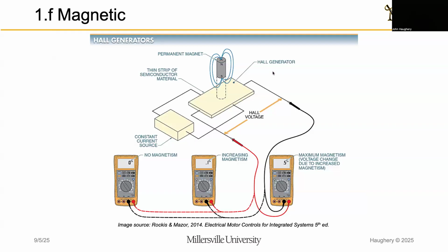And of course, I can use that voltage to drive a solid state relay. So the input, or the quote unquote coil part of a solid state relay, to turn it on or energize it to then change the contact output on that solid state relay. So Hall effect sensors are a very common sensor that we use by seeing or not seeing a magnetic field.